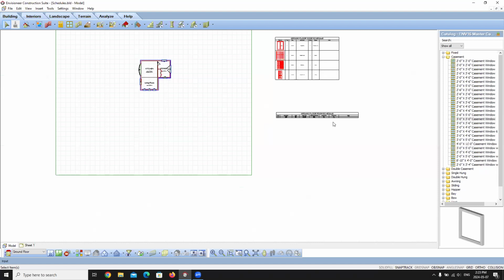Floors, ceilings, and roofs have framing information attached to them in their properties, but their members will not report in a member schedule unless you convert their framing to members first. Just a note here, building essentials and construction suite users will need to use the structural floor tool to add in your framed floor in your designs. So you can use the basic floor option and apply a member to it, but the structural floor is by far the more accurate way of doing it.